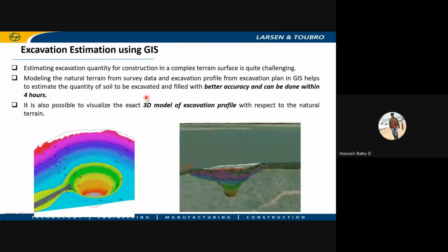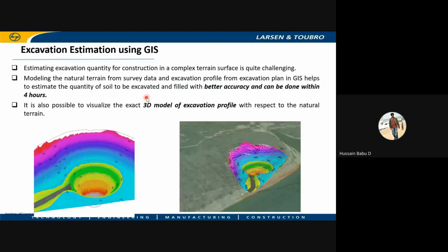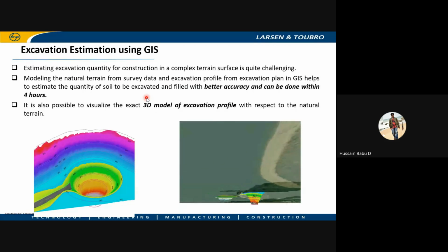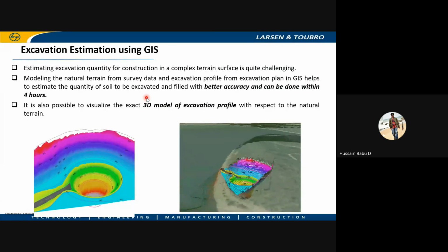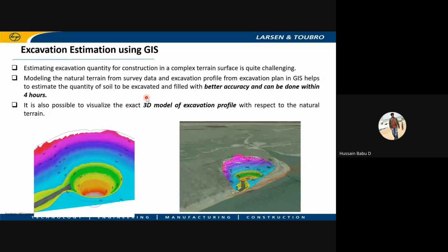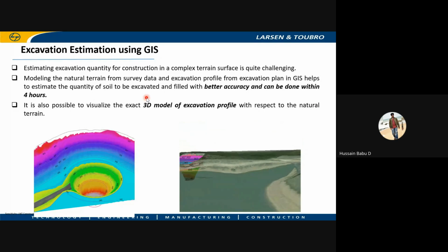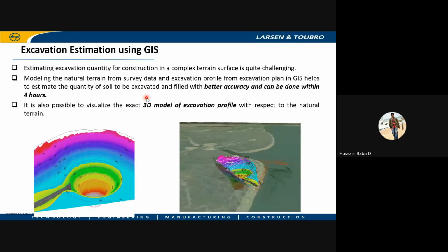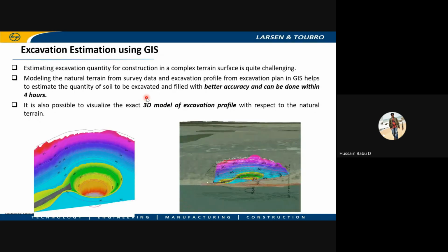And this is another excavation estimation in JS. As we see for all our pump houses and intake structures, we need to do huge excavations, which can cost around 50 to 60 crores sometimes. As you can see in this imagery, the top is around 363 MSL, and the bottom is around 325. So almost 40 meters of excavation is required for this kind of construction, which will cost around 50 to 60 crores in these cases.